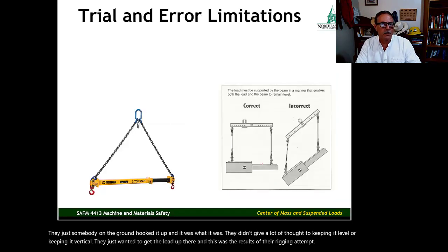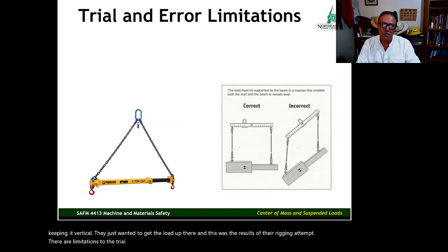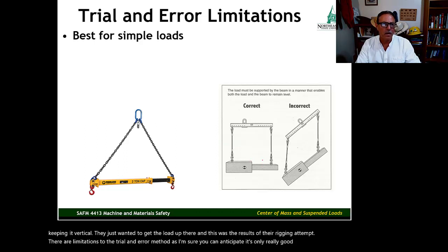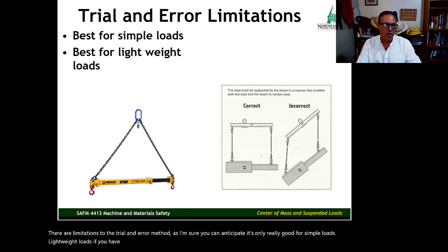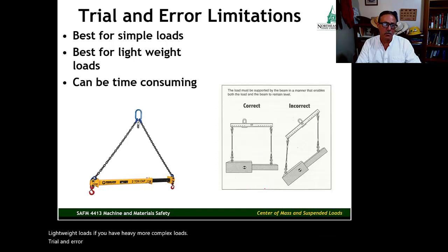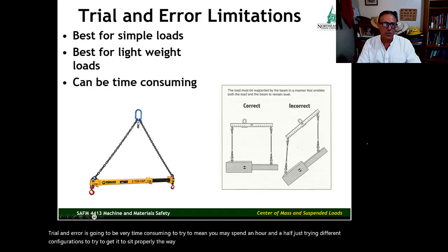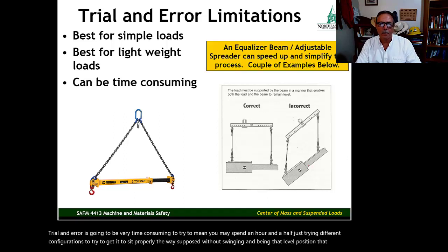There are limitations to the trial and error method, as I'm sure you can anticipate. It's only really good for simple loads, lightweight loads. If you have heavy, more complex loads, trial and error is going to be very time consuming. You may spend an hour and a half just trying different configurations to get it to sit properly the way it's supposed to, without swinging and in that level position that you want it in.